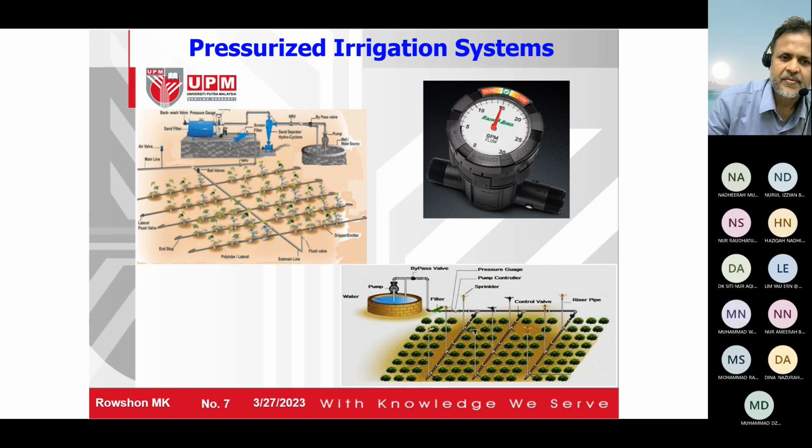So that's why in a micro irrigation system you need the filter, because it is low pressure. It is pressurized but low pressure. And sprinkler is pressurized but high pressure. This is the difference. So when water comes with high pressure, the sediment cannot get stuck here. This is called the sprinkler nozzle. Sediment doesn't get stuck, but if there are some particles in a micro irrigation system, they can simply get stuck here and block it, because it is a very small, narrow, very tiny opening.